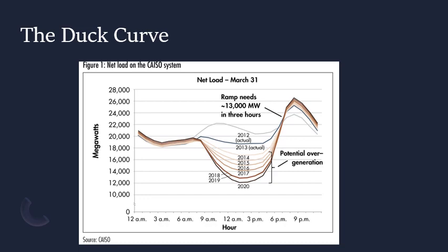And as more solar panels have come online in California, that net load is declining, right? Because there's more solar providing electricity, particularly during the sunny hours of the day. That's why you can see the belly of this duck dipping down over time. The real issue here is that going from about maybe 4 p.m. to 7 p.m., we need a ramp up of 13,000 megawatts in capacity.